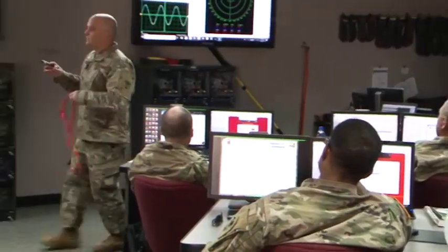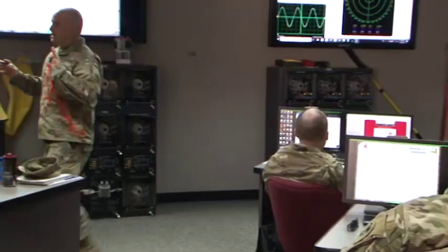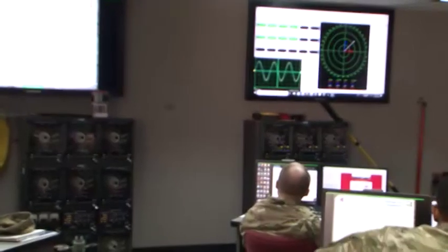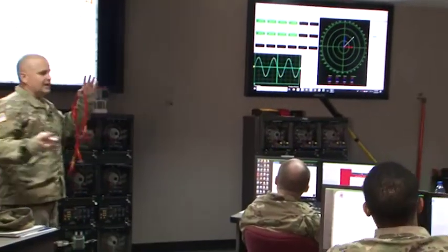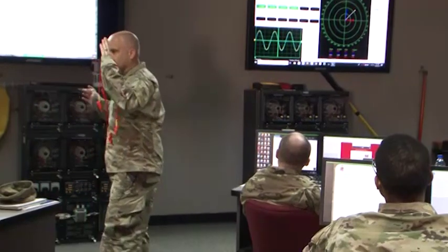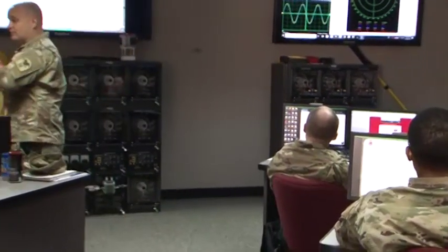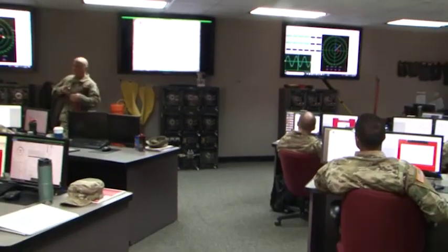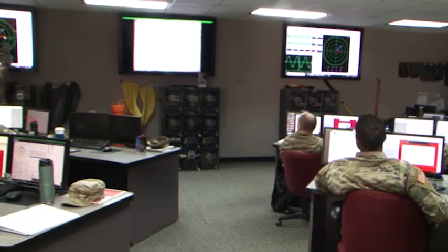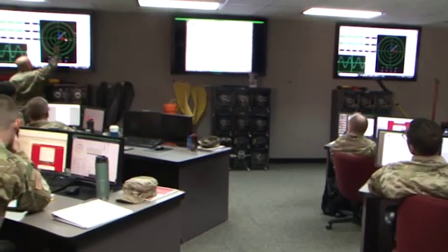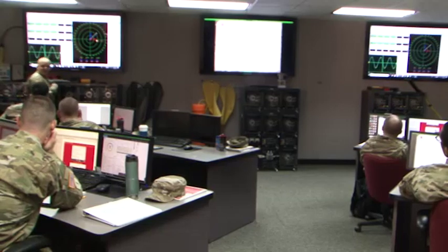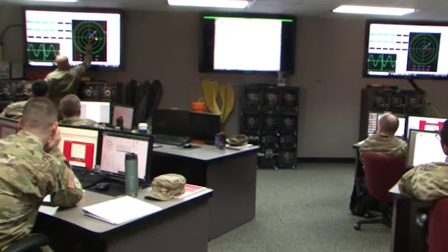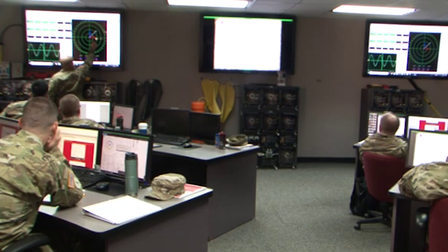So now I'm just looking at the varying degrees of the voltage vectors. I'm seeing that one is here and one is up here. There's a 90-degree shift, well, 88 point something degree shift, between the voltage across that inductor and the current going through the inductor. And there is a 0-degree phase shift between the voltage and current going through that resistor. So going back to what you said yesterday with the vector math, I'm looking at these two vectors, this one and this one. Blue, that's E2, going across the inductor. The red one is kind of hard to see because both colors are right on top of each other, and their magnitudes look almost the same in scale.